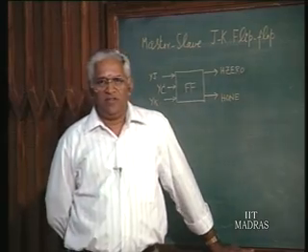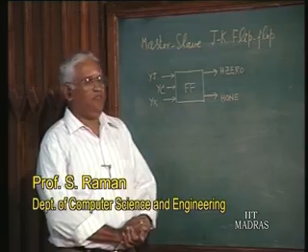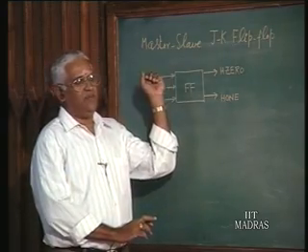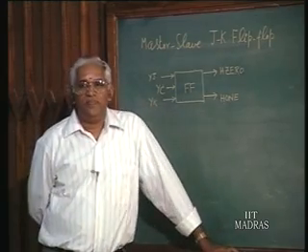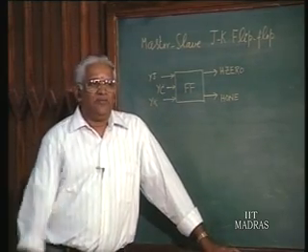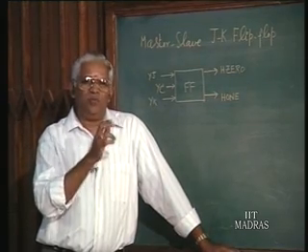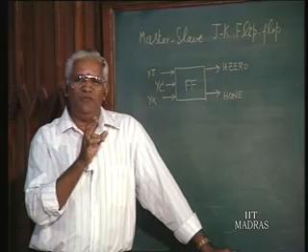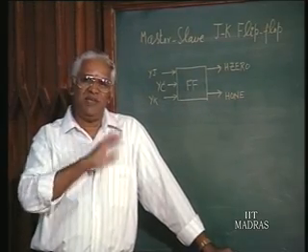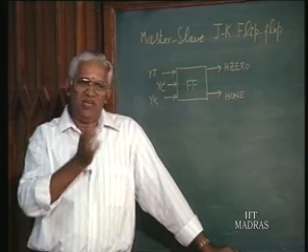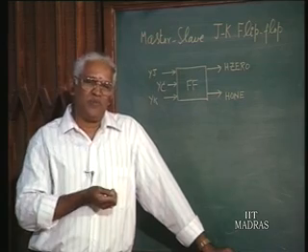Towards the end of the previous lecture, we considered the design of JK flip-flop, specifically master-slave JK flip-flop. We just started that. Why did we take up this particular design? Mainly because this particular design will involve a few states, a couple of inputs and a couple of outputs to deal with, and hence only a few states to deal with, and then the whole design can be explained both from the hardwired control point of view as well as from the micro programmed control point of view.